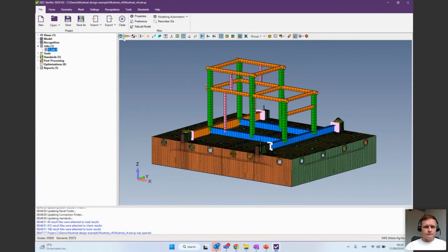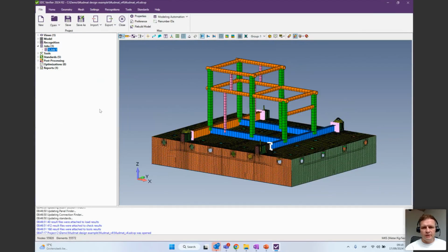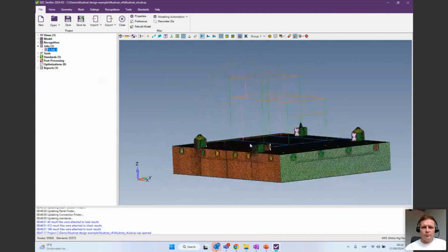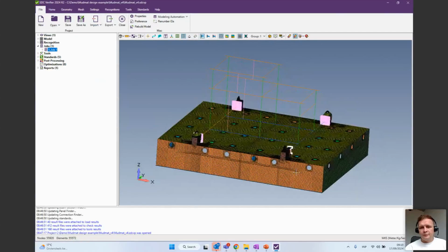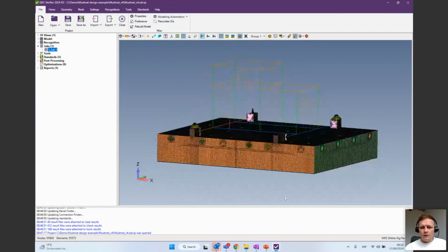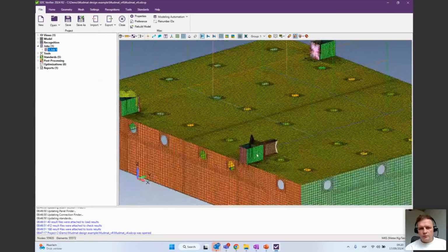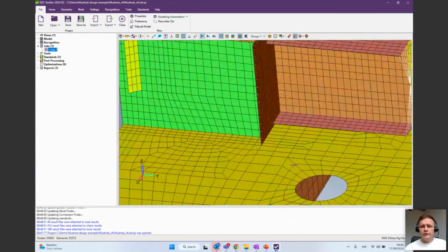All right. So what I wanted to show to you today is first and foremost the new codes. Well, let's explain our model a little bit. I'll turn the thickness off so you will see. This is a model of a simple structure, kind of an offshore mud mat with plates at the bottom to be able to run plate buckling checks and weld checks, as well as bolted connection between these panels over here.